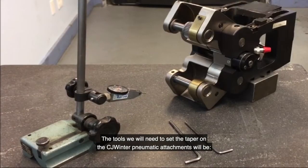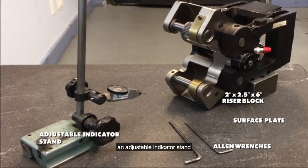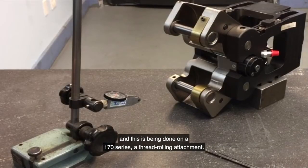The tools we will need to set the taper on CJWinter pneumatic attachments will be a surface plate, a 2 by 2.5 by 6 riser block, Allen wrenches, an adjustable indicator stand, and a 1/10 resolution indicator. The first taper setting we will do is the Type A double dog point, and this is being done on a 170 series thread rolling attachment.